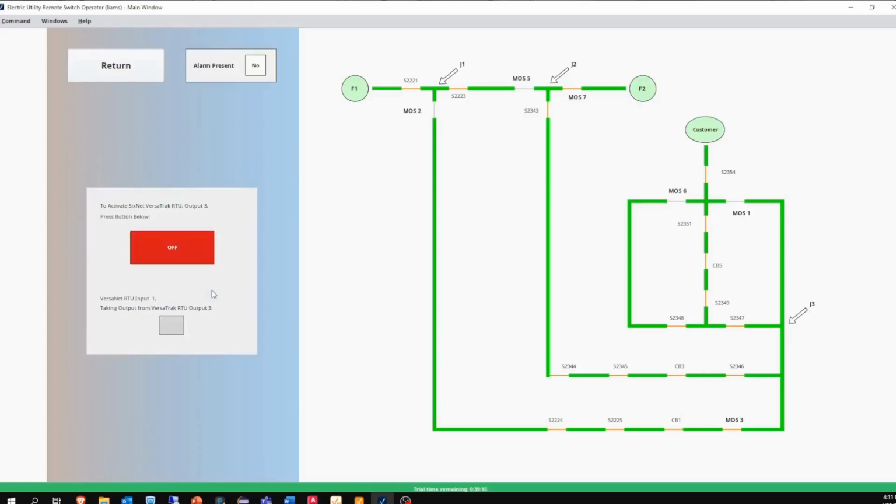In the 6net window, I demonstrate interoperability with a different brand of equipment from the GE MDS radio using Modbus protocol. I wired this RTU with a single output, which sends its output to a single input on the same RTU because, again, the emphasis here was on interoperability with this different RTU and not to actually interface with field equipment. I'll demonstrate that HMI successfully reads and writes the tags from this RTU.